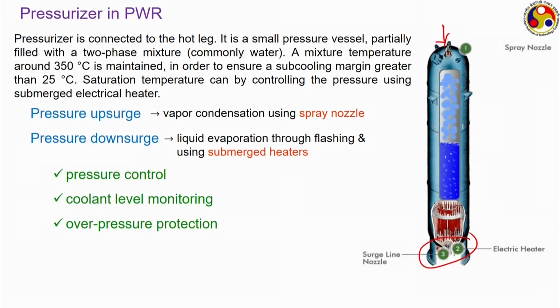However, if the safety valve is not sufficient, there will be another emergency protection valve on the lid of the pressure cooker. So, in case of emergency, that opens, allowing some further release of the vapor phase. This overpressure protection is also somewhat of a similar kind.